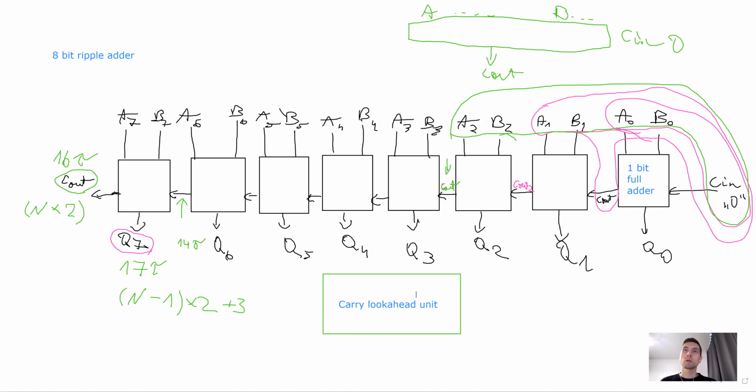So it's a logic circuit which calculates each carry only from the inputs. Theoretical maximum speed would be 3 tau. If we do this entire hard work of Karnaugh map and something like that, from a truth table, we can write any term equal to NANDs of some combinations of input terms. So generally any expression in binary can be converted to simple NAND with 2 levels and the NOT in front of it.